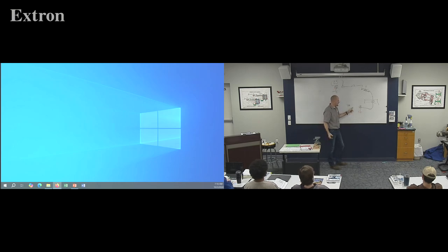Because the component's trying to draw amperage, but this would be a high resistance, and Kirchhoff's law would say, well, the high resistance is going to eat up a bunch of our voltage drop, and we only got a little bit left out here. So that would be kind of a common place to look, and yeah, you could use an ohm meter, and you could check resistance all the way across that. We're expecting 0 or close to it. So that is a way to do it.